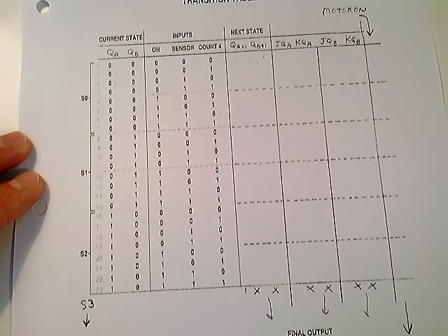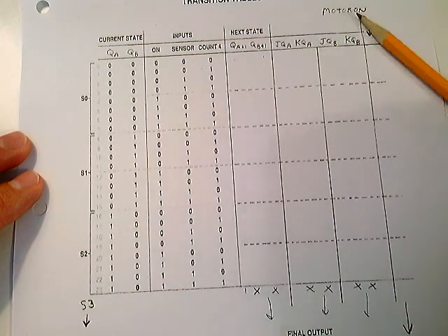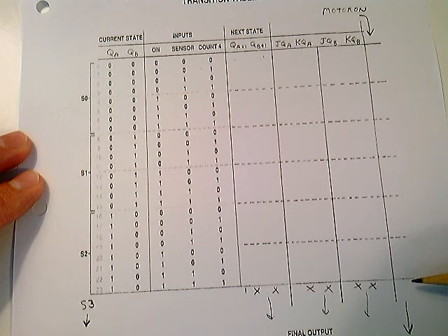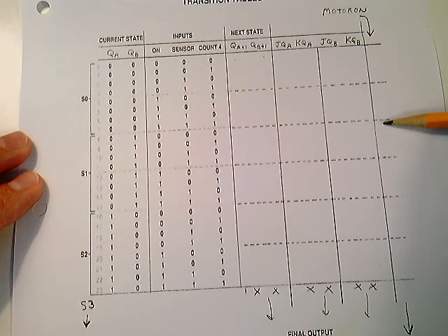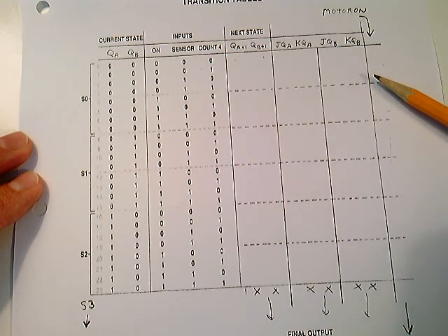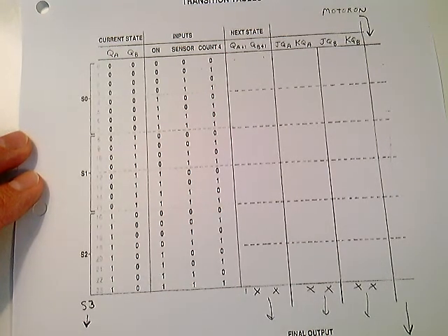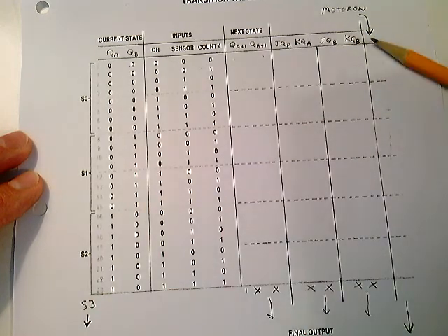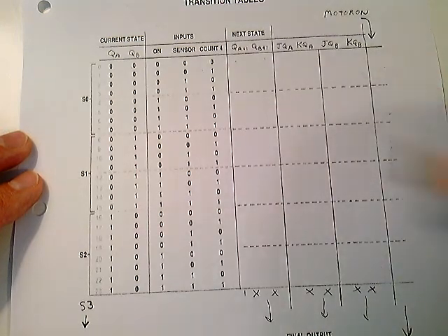Here's your final output. Your final output, go ahead and put the motor on. When's the motor on here? Most of the time the motor's off. But the motor's on when you're in state number 1. So you can see when you're in state 1, your 1's here, 0's every place else. So that's going to define your motor on output, your final output for motor on. You can see down here that truth table. Pretty easy to do. You can do a K-map for that, but I think you can see you're in state 1. That's when the motor's going to be on. Implement that logic as simply as possible.